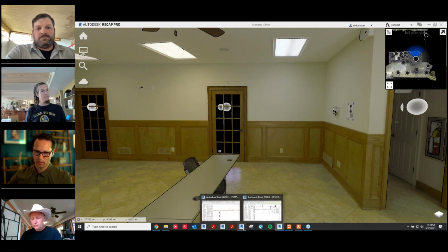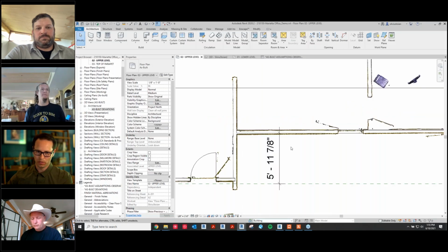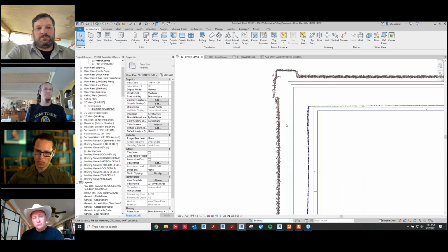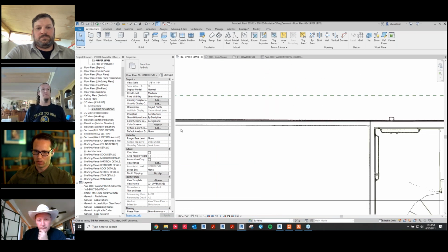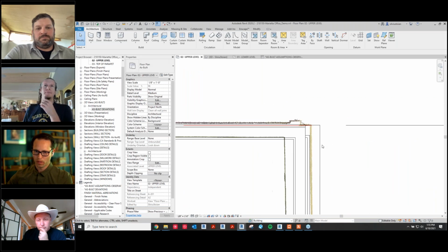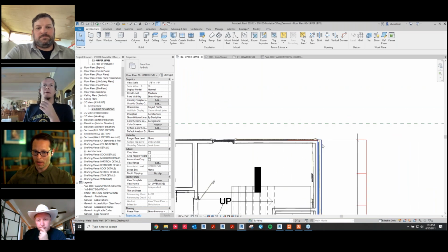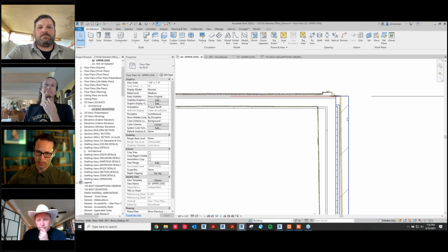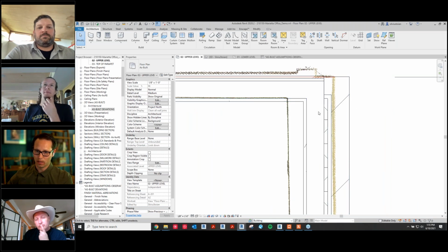as in this case, let me switch back to this building. If I go to some of these corners, you see that I'm off by about 2 inches and about 4 inches on the other side. So yeah, I need to make sure that my envelope is first modeled. And if I need to model everything orthogonal, I communicate to the team, like, hey, these walls are not orthogonal.